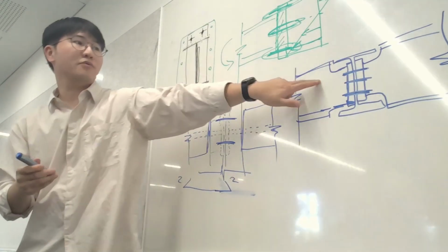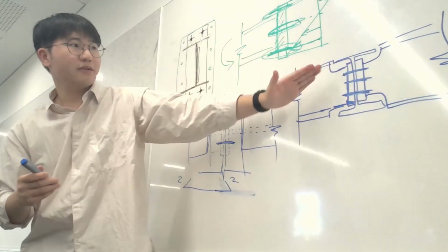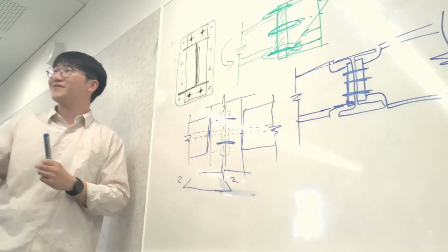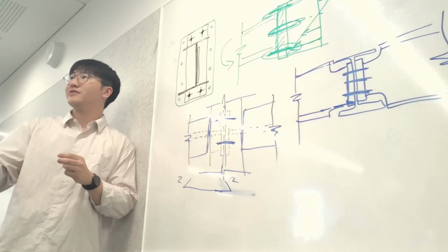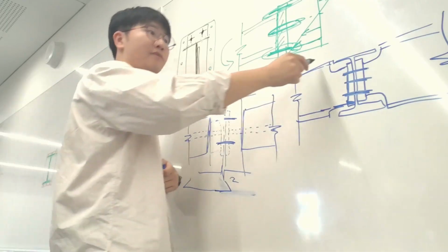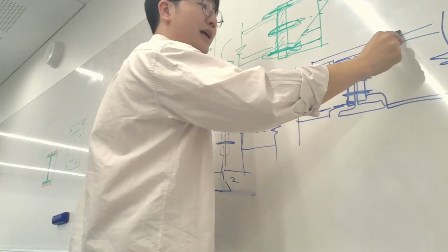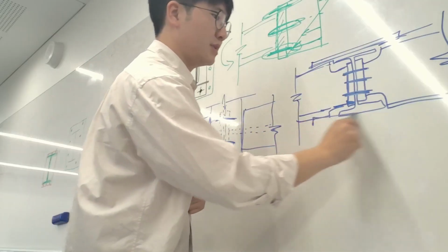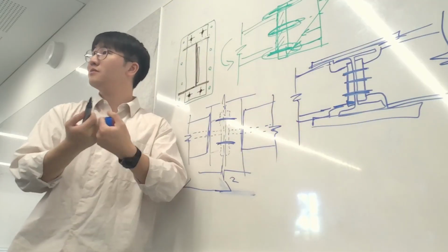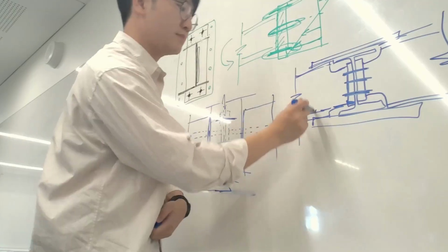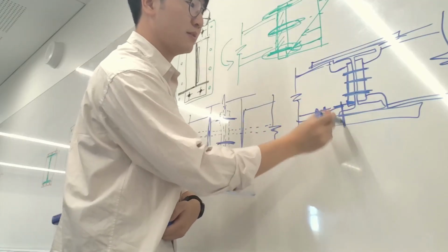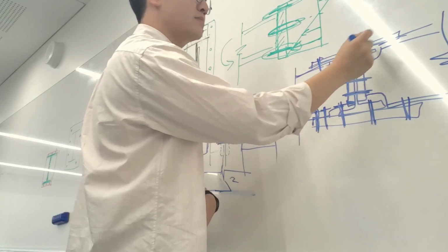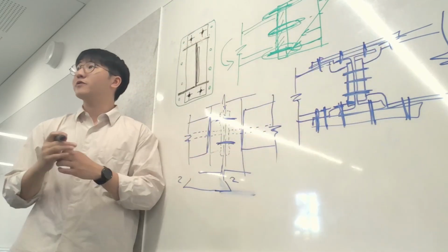So you've basically got a double cantilever thing, but it's still allowing a bit of rotation because these two things aren't connected together. But do you remember, in week 4, Andy, how you suggested doing something at the top here? Oh, yeah. We actually do add a stitch plate at the top and bottom. And this will make it fully rigid, like connected together. Okay. I see. Because that stitch plate doesn't allow either of them to bend separate from each other.